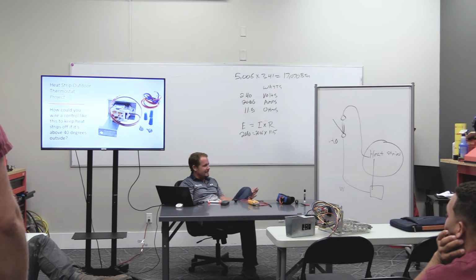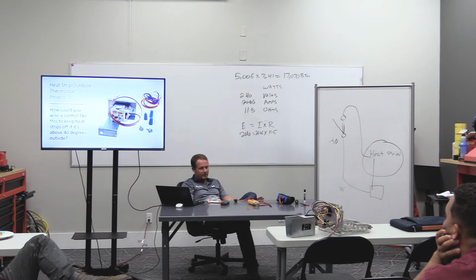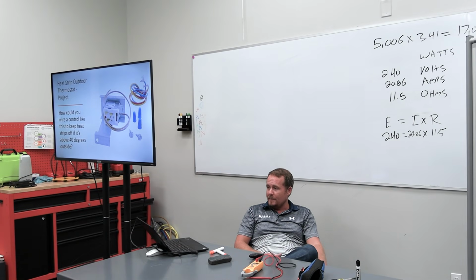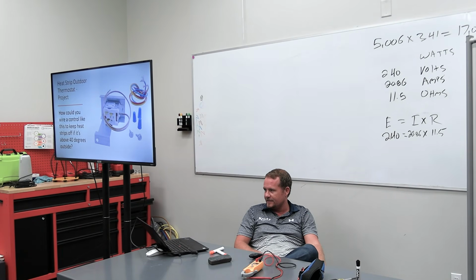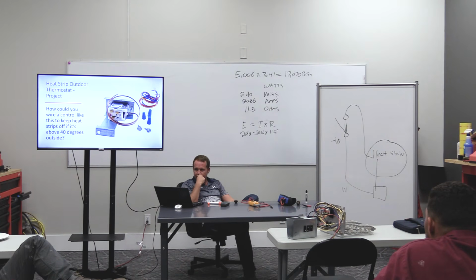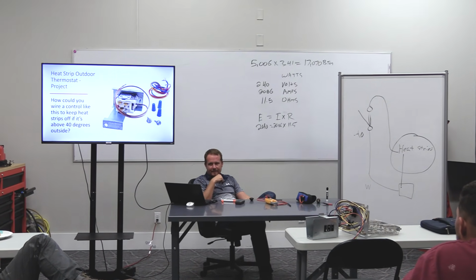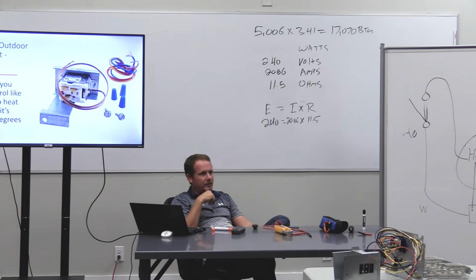Yeah, and so this is not incorrect. It's just not really explaining exactly how you would do it. One way, the way a lot of people would do it, is they would use two separate wires, run those out, and then make and break inside the air handler. But that's a waste of a wire. You need a switch, like a safety switch on the inside, breaking it. Yeah, but you have to use two wires in order to do that all the way to the outside.